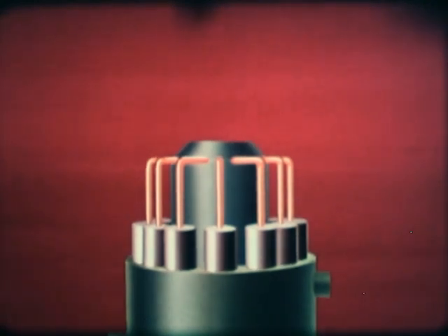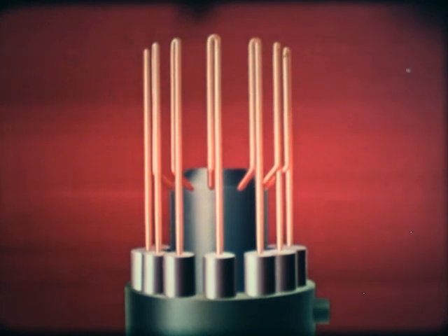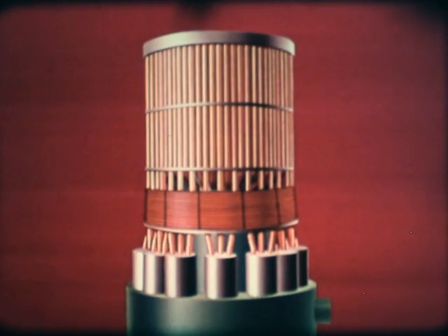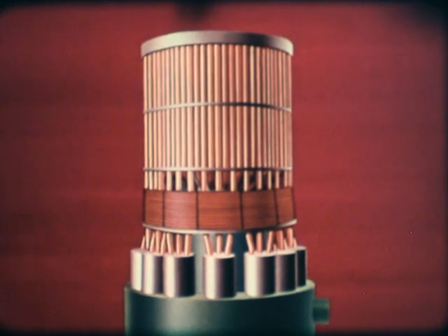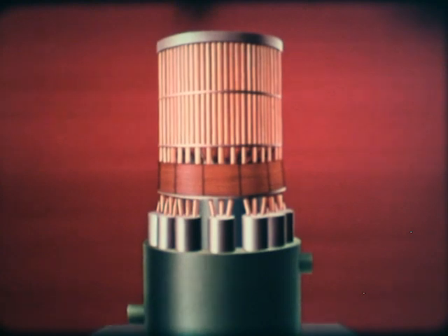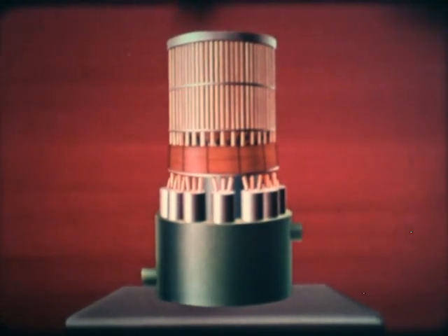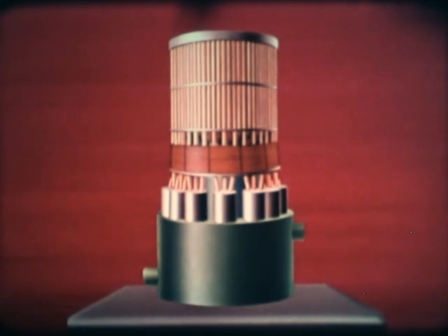The heater is improved by extending the heater tubes, increasing their number, and adding fins. The exact dimensions of the heat transfer system result from a thorough investigation of the Stirling cycle and have been evaluated electronically to minimize the sum of all the losses.